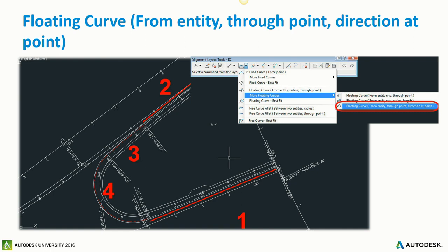So it has criteria, it has constraints from the highway design manual from Caltrans at every point. So based on the typical section that will be on these two highways, these two ramps, the distance between the ramps at the start of this is about 22 feet. You got a lane, you got a shoulder, and there's a distance between them. Based on those two, my criteria is that I need to start the alignment 22 feet away from the known ramp that I already have. So that red line that I show there in the south end, that is my first tangent for the alignment I'm going to create, and my criteria is to be 22 feet away.